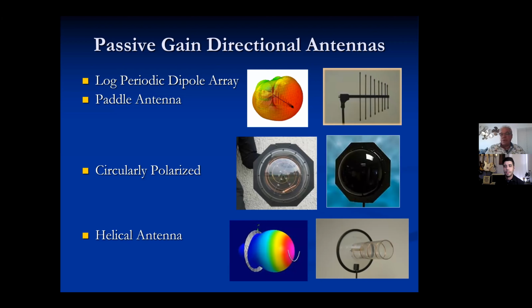I wanted to do this on Broadway in the 1990s. I wanted to use a patch antenna, a fractal patch antenna. I can't believe nobody's doing this yet. I think maybe Shure's MicroPack might now implement some type of patch, but someone from Shure is going to have to verify that. But I've been wanting to do this for over 30 years. Get rid of the whip, go ahead and use the SMA connector. And what I was told by many manufacturers at the time was it's a licensing issue. You have to license this antenna.